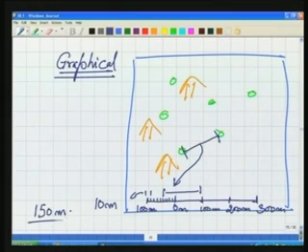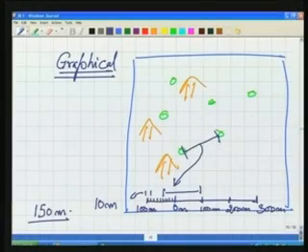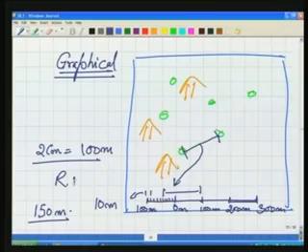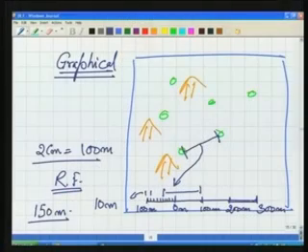So, graphical scale is nothing but a graphical way of showing your scale, because in this case this distance is 2 centimeter. So, 2 centimeter is equal to 100 meter. So we can write the corresponding engineer's scale also, we can write the corresponding RF also. The only difference in this case is that we are showing the scale by drawing a line on the map itself.